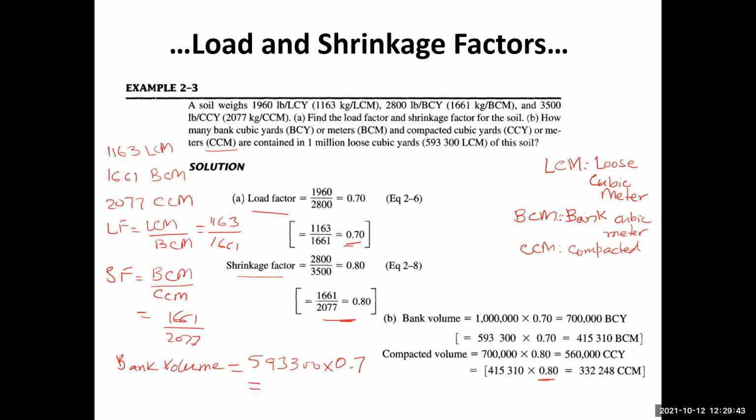Okay, we simply have to multiply the volume in the respective condition with either the load factor or the shrinkage factor to find the answer. If we want to find the volume in the bank condition, you will use the load factor.